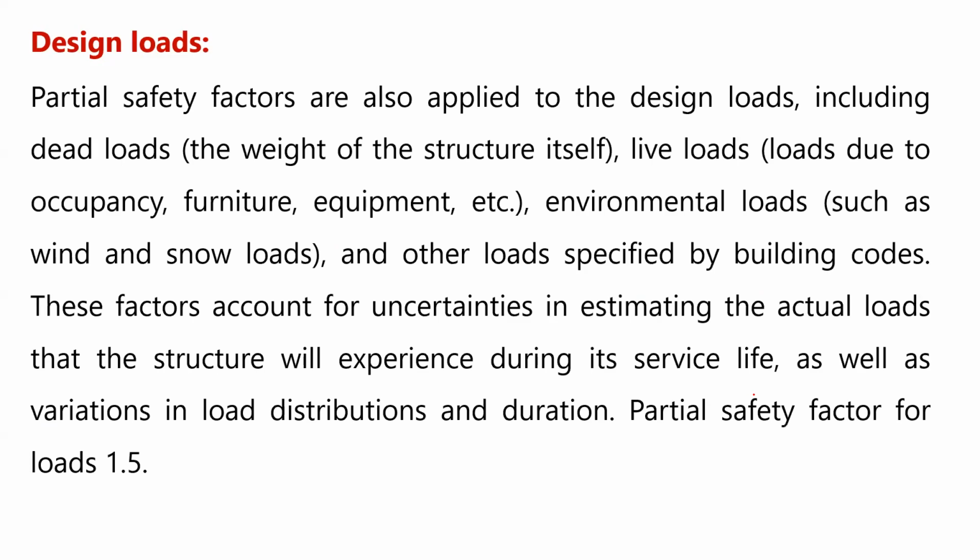Then we have second, design load. Partial safety factors are also applied to the design loads, including dead loads, live loads, environmental loads, and other loads, that means all loads which are specified by building codes. These factors account for uncertainties in estimating the actual loads that the structure will experience during its service life, as well as variation in load distributions and durations.